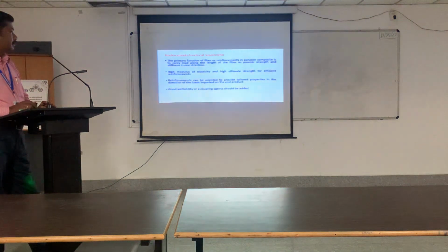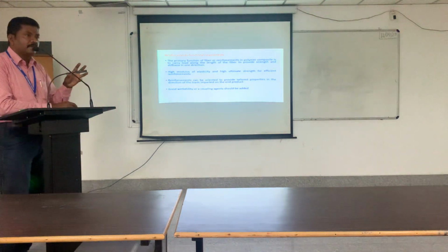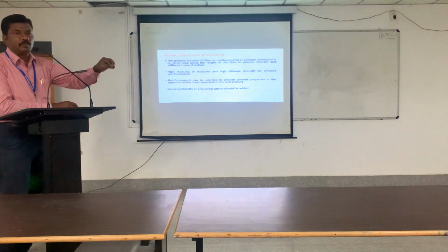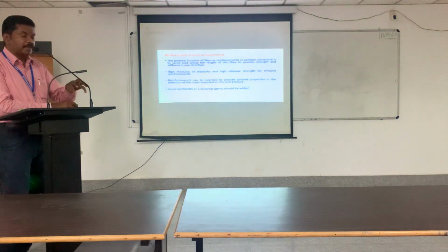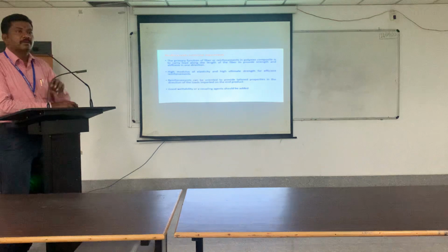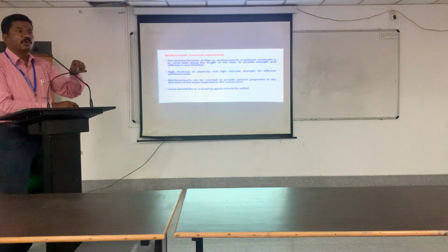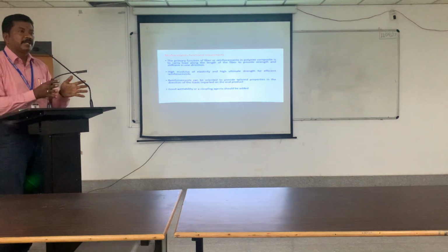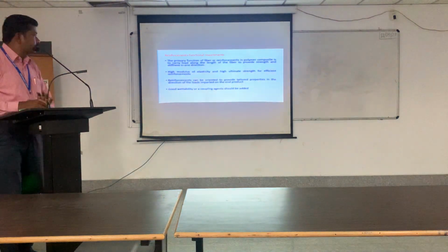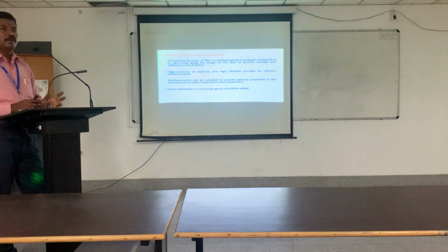Good wettability, or a coupling agent, should be added to get more strength. If the matrix does not wet the reinforcement properly, you need to add some more additives. Even in the case of masonry works, the cement and water mixture made earlier does not wet the brick completely. You should add more water, so that the water and cement mixture becomes thinner, and that will wet the bricks very quickly. Or any kind of coupling agents, additives or chemicals, whatever it may be, can be added to increase wettability. If the wettability is higher, then the strength will be higher.